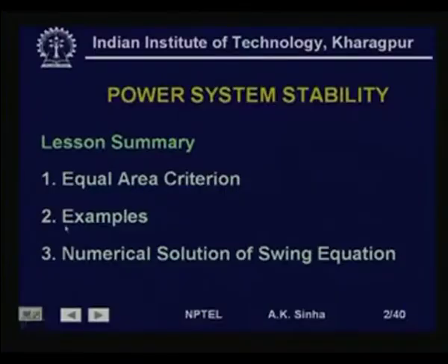We will take up an example on this, and if time permits, we will talk about the numerical solution of the swing equation itself. So, instead of using the graphical solution that we can work out for a single machine infinite bus system, we will talk about the analysis where we have a number of machines in the system, that is multi machine stability analysis. There we certainly need to do the numerical integration of the swing equation